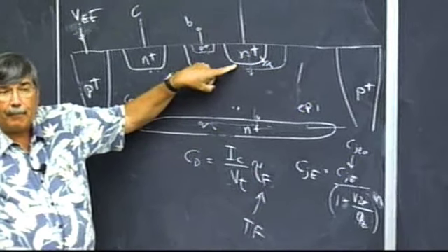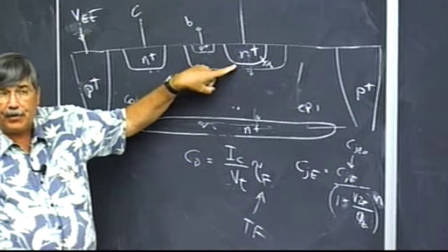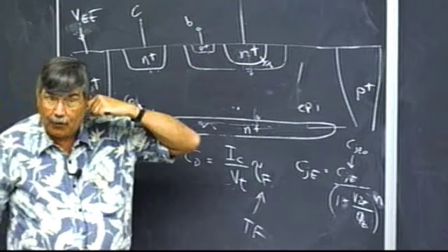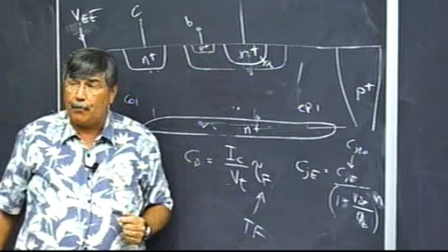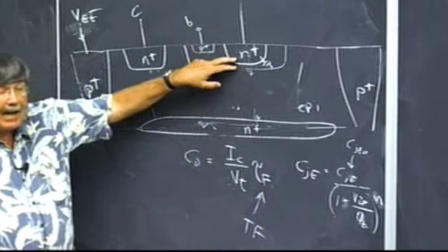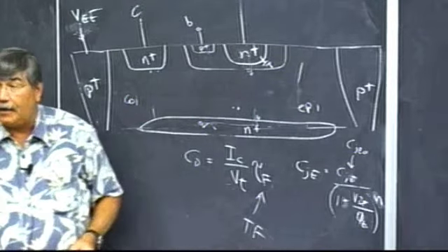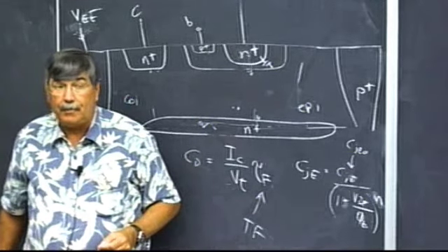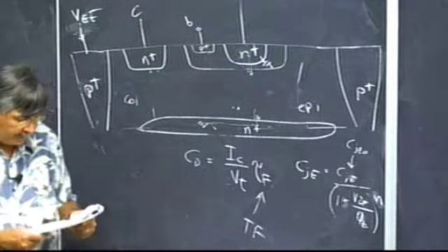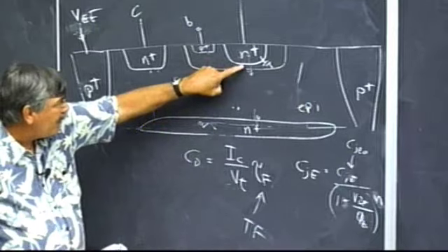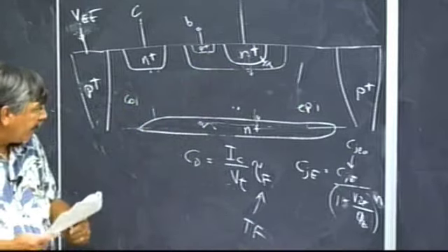The base-emitter reverse bias breakdown voltage of a typical transistor is about 5 volts or less. That's actually pretty important. You've got to be really careful if you accidentally reverse bias the base-emitter junction, it can be damaged because of too much current flow or almost anything. So it's very sensitive. We really have to be worried about what goes on physically down in here.